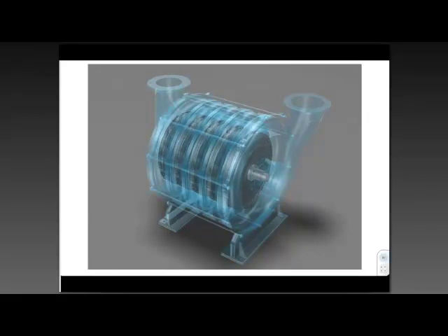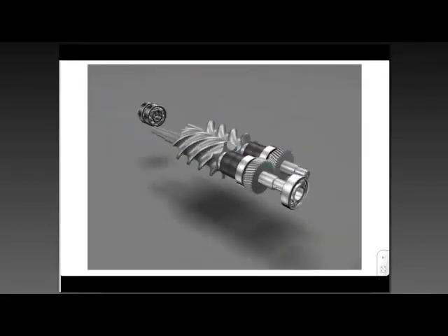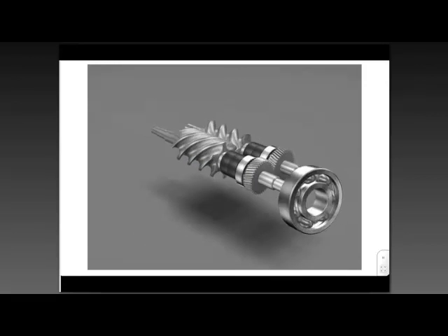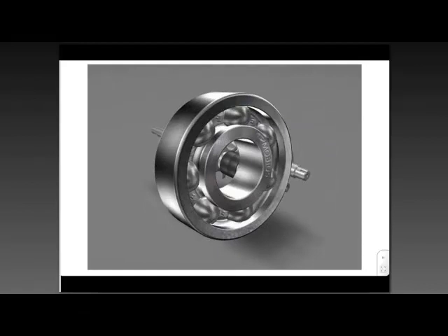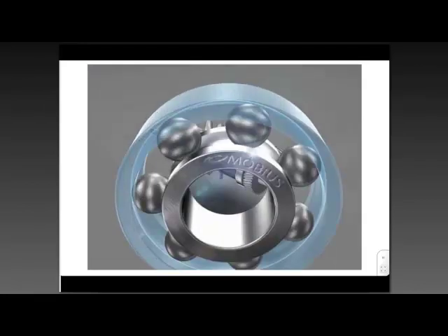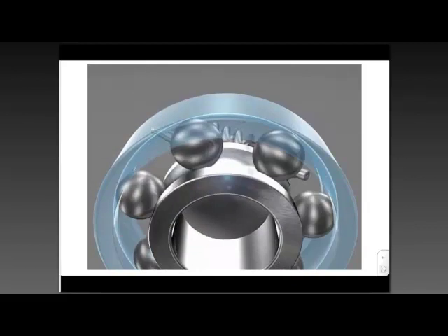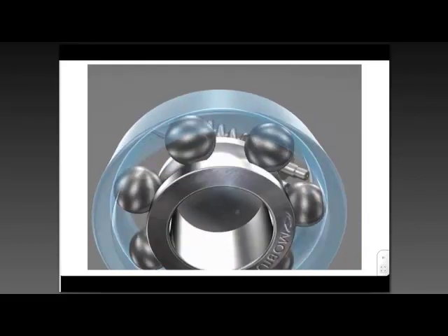Because if we can understand what's happening, for example, inside the bearing, and we can tell whether the balls are just rolling along smoothly without any damage to the raceways or any damage to the rolling elements, then that gives us a clue. If we can tell that there's a lubrication problem that might lead to a further problem, or a misalignment or an installation problem, that's important.